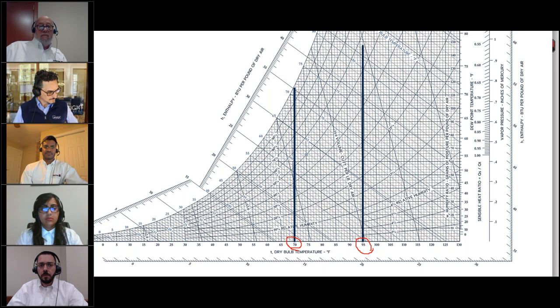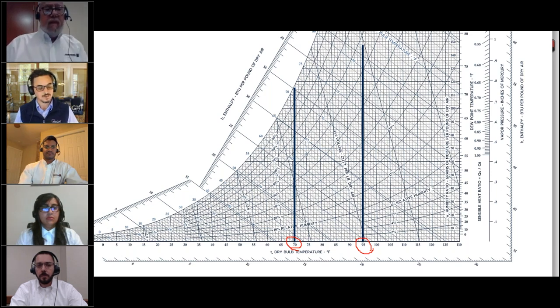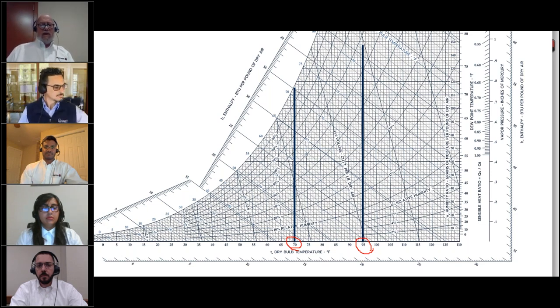Is there a smartphone app for measuring wet bulb? I know there are apps that will calculate the psychrometric properties, but I don't know that there's one that measures wet bulb. Does anyone know? Maybe there's some attachment you can get to an iPhone or a Bluetooth device that connects. There are a couple of different devices out there that you can get as attachments, basically Bluetooth, that you can link to your phone. And at last time I looked, there are probably half a dozen psych chart programs available through the different app stores. I have a couple of them on my phone from a couple of different manufacturers. They're rather useful because I've gotten to the point where I don't carry a paper psych chart with me anymore, and it's easier to do it on my phone. Yeah, good question. All right, next one.